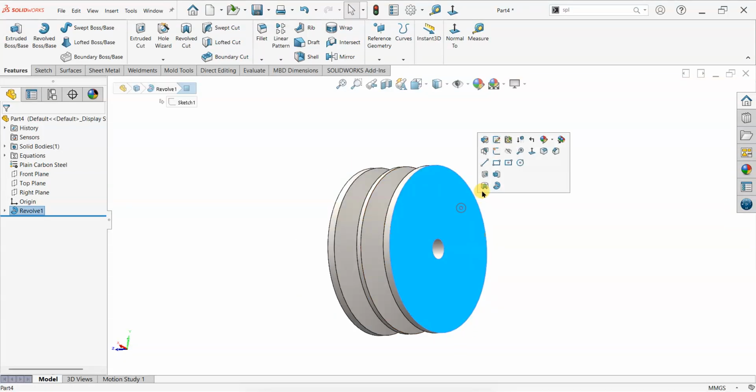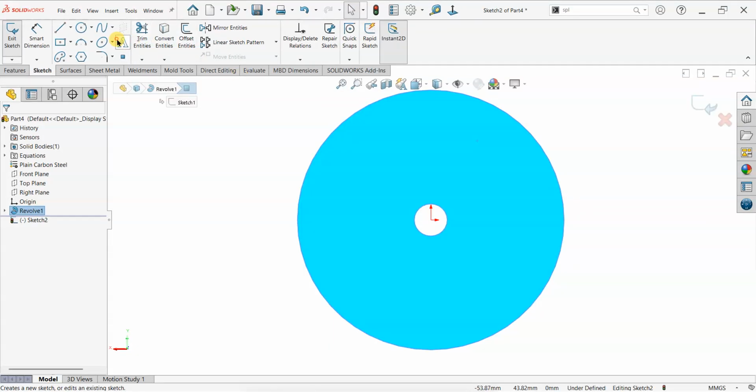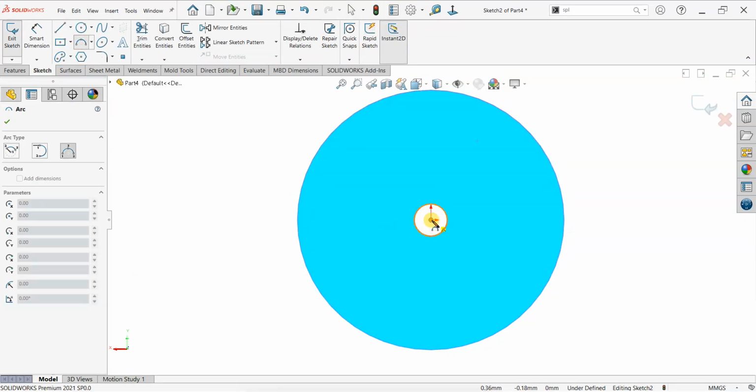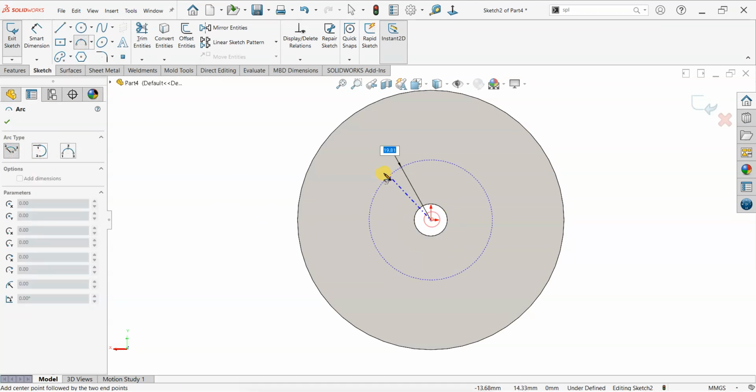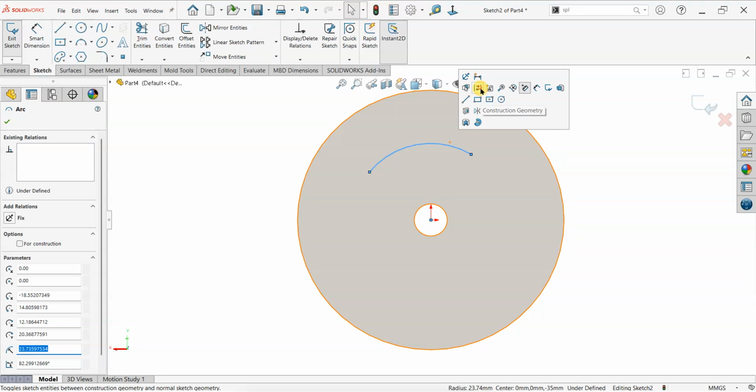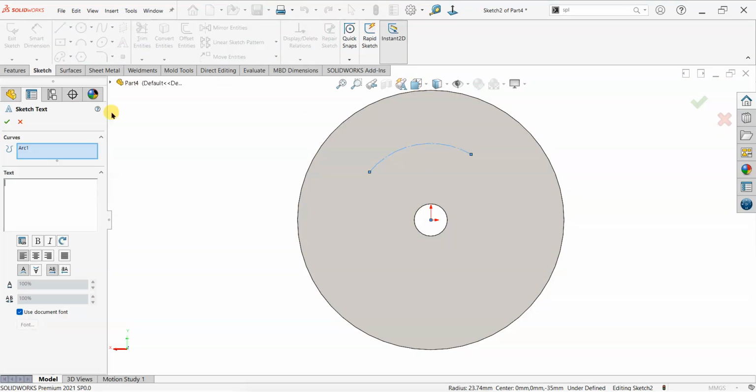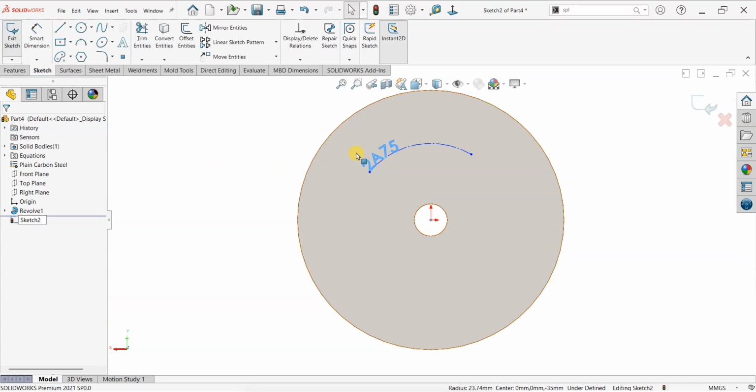We can also make an impression of the size of our pulley. I will click here. I will select this. I will say A type pulley, A type pulley 75 mm as diameter, pitch circle diameter. 2 means double groove. A means section of pulley. 75 means pitch circle diameter of pulley.